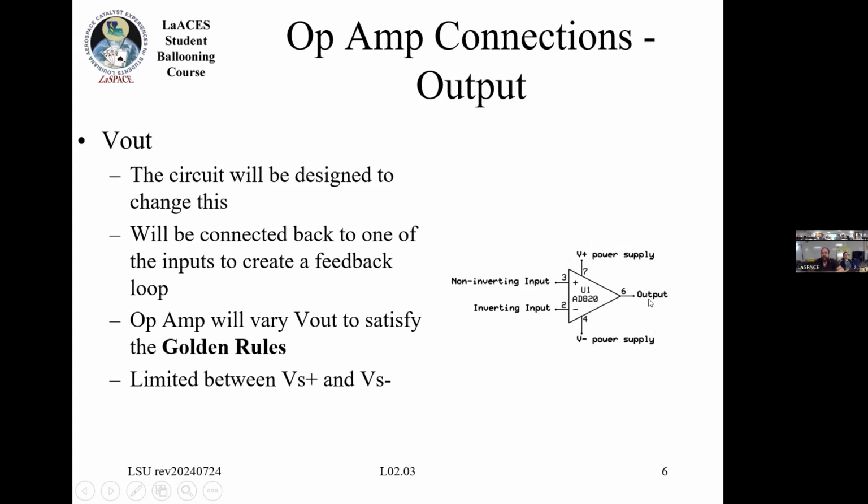Like I said, the range of values that you can get on this output is between whatever you have on the positive power supply and the negative power supply. So when you're designing or building one of these, you consider, okay, where do I need this output to be? Therefore, I have to have these values on the power input. Okay.